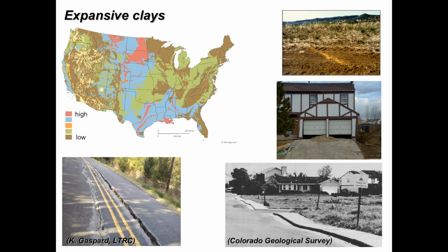A little bit hard to see, but particularly within this garage area, which is very lightly loaded. I mean, there's probably just a 4 to 6 inch concrete slab overlying the natural material. So it's these lightly loaded structures, things like small story houses, pavements, that really experience the most damage because there's not enough downforce to resist the upward heaving that's occurring.